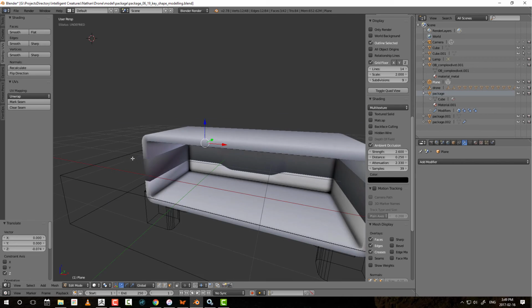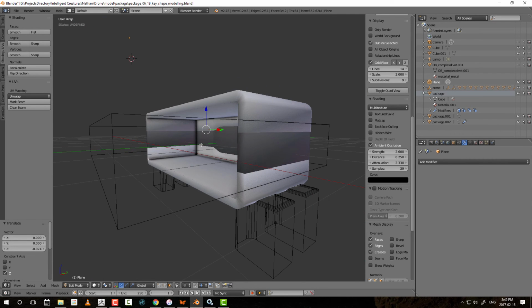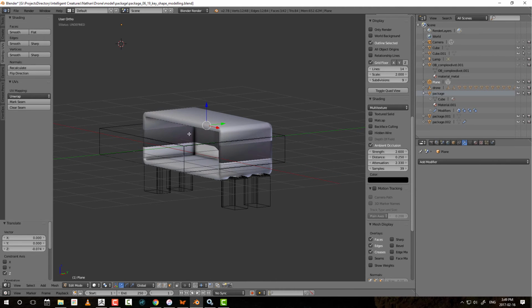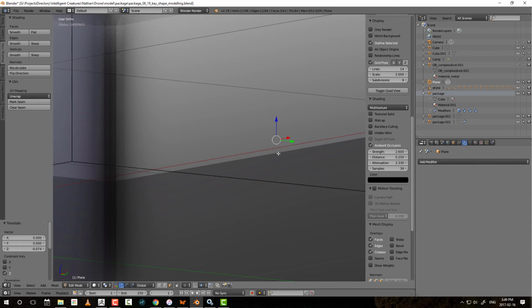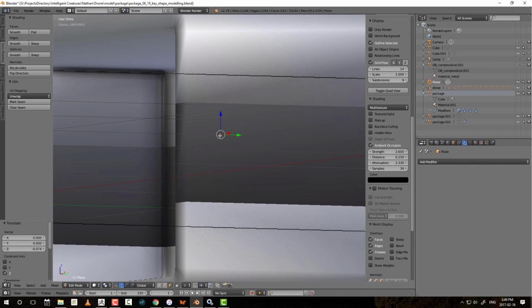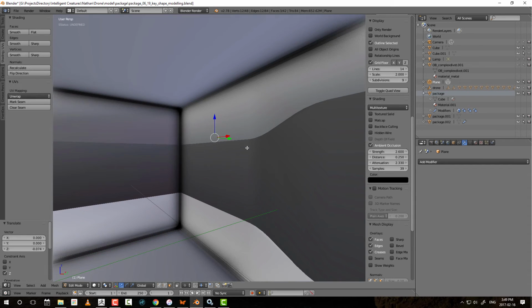Now, the other thing that might screw you up, I guess, is that sometimes when you're in orthographic mode, right, and I just pressed 5 on my number pad, and I'm navigating around, it's kind of hard to work because, oh, now all of a sudden the back wall is in the way. This is why you really sometimes have to work with and sometimes without the orthographic mode.